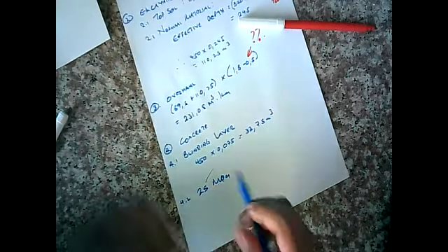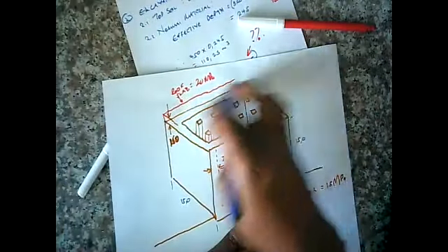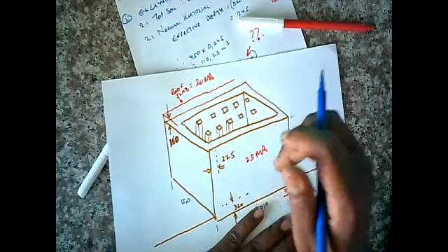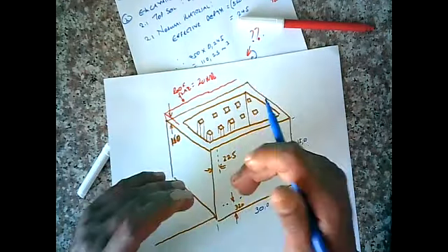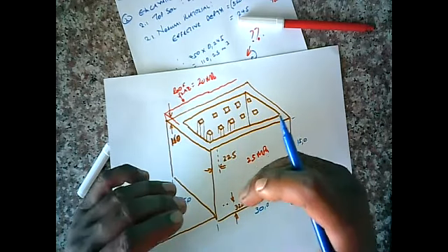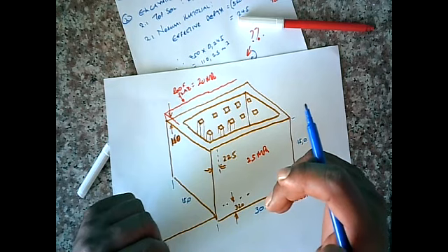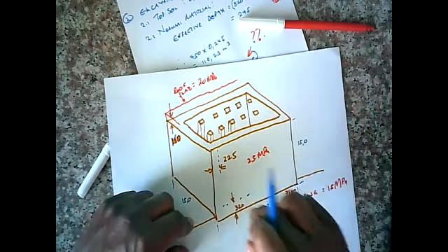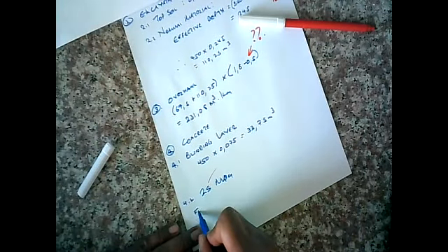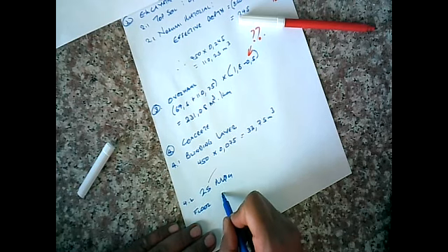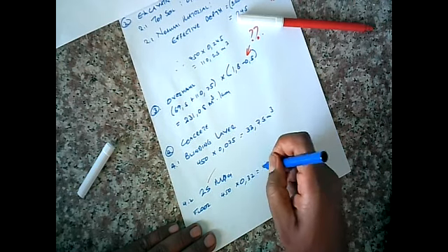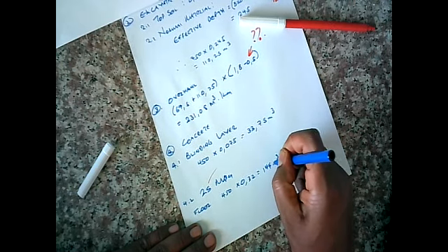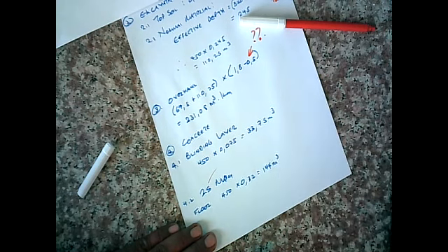All right, now 25 MPa concrete is basically all of the structure except for the roof. So let's break it down in order of construction. We're going to put the floor first, then the walls. Not vice versa. So let's calculate the floor concrete first, and let's be methodical. Floor concrete is 450 square meters times thickness of 0.32, and we're getting 144 meter cube of floor concrete.